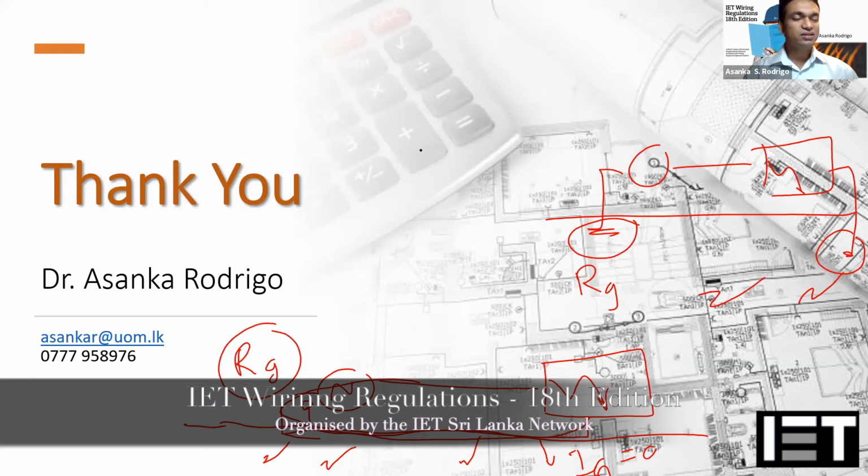In that case, I don't see there is a requirement. For example, if you are giving mechanical protection for your cable, for example PVC cable with a PVC conduit, so that you are giving the mechanical protection as well, and it is not going underground, then as I said, you don't need the RCD. You have to keep in mind there is no point of asking for an RCD, because even if there is an earth fault it will not be detected.